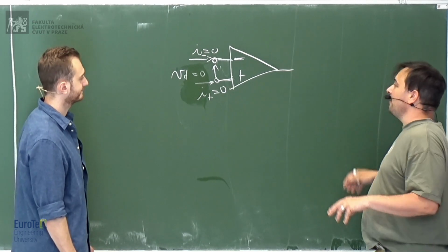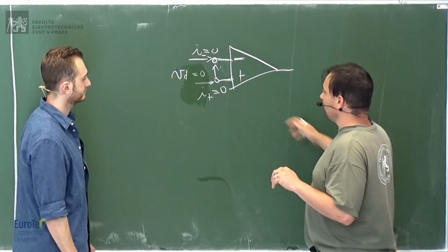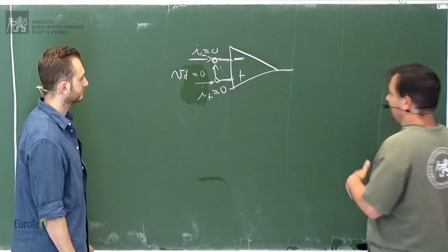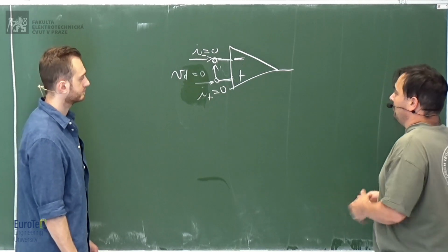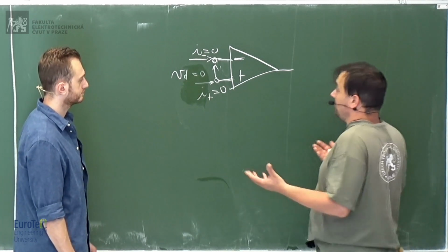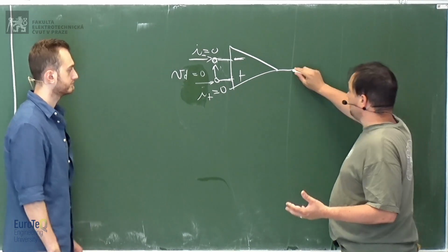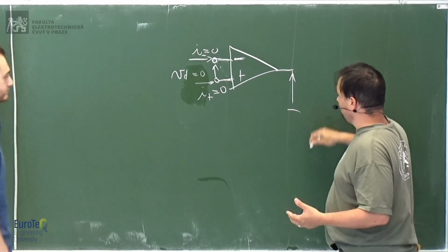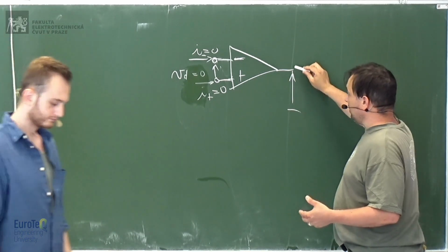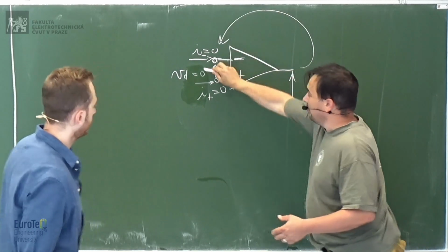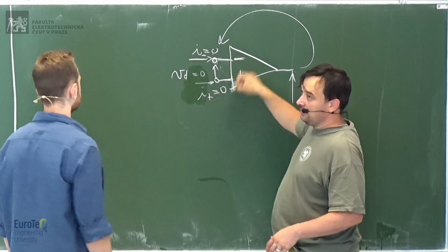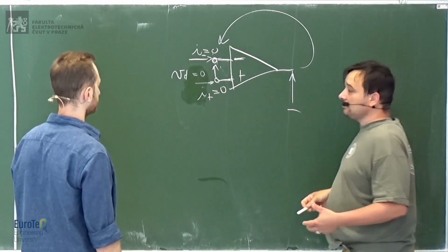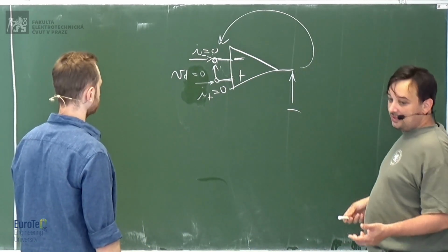Which means that once you apply this, and Kirchhoff laws and all other basic circuit theory laws, you can solve any circuit. Because you don't know which is the output voltage here, but it will do everything to have VD equal to 0. So you impose these three conditions to your circuit, and then you solve everything else.